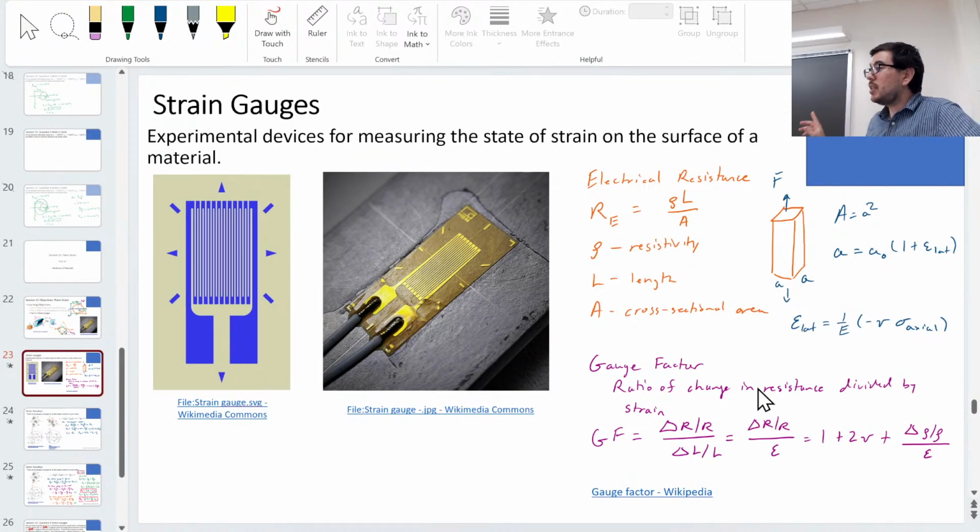Now this is just more practical information, but the attachment of these gauges is not trivial. You need to have very good contact between them, and the strains that you measure can be very, very small. And you've already seen in the problems, often we're talking about microstrain, tens of microstrain, hundreds of microstrain. So if you don't have very good intimate adhesive contact between your strain gauge and the object, if they're slipping relative to each other, then you're going to have issues. So when you shop different websites for strain gauges, don't just buy the strain gauge. Look to see which adhesive they recommend as well.